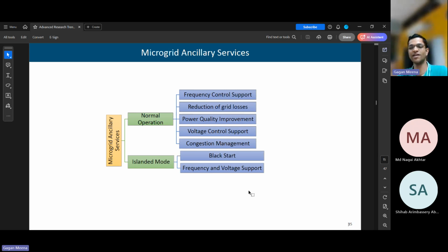Because microgrids are already small pockets or zones, if they have sufficient generation, they can start with the critical loads. Slowly all these zones can be connected, and once all the zones are connected, the thermal generators can be brought up, and the entire restoration process can be made very fast using these microgrids. If storage is also there, it will be a part of it and will also help.